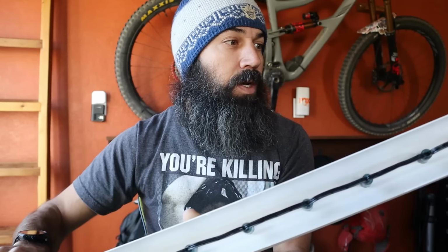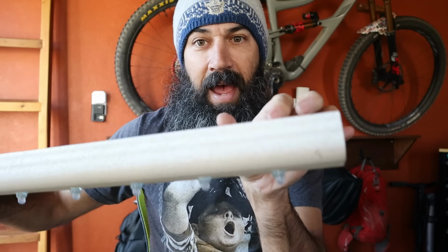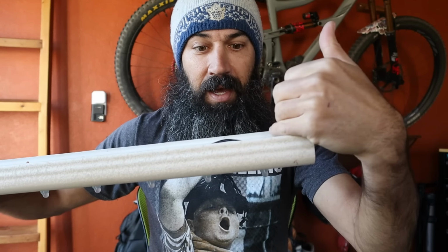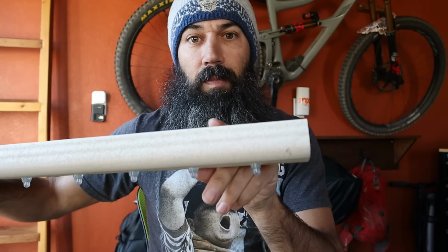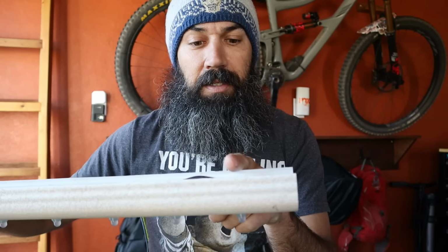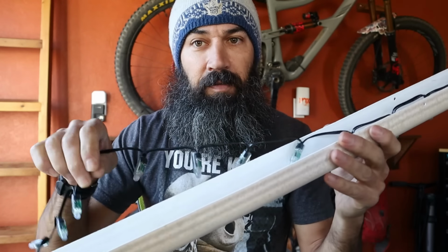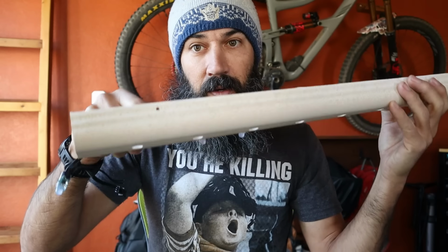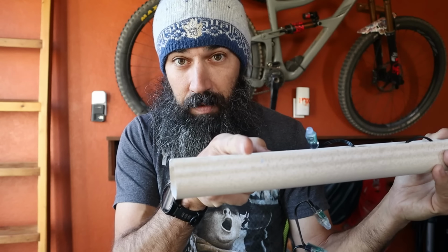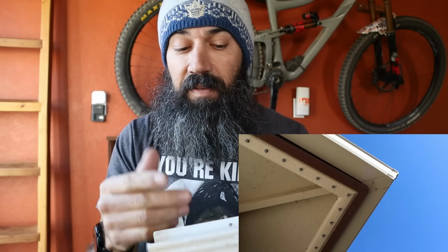So what I ended up doing was my starting hole, I always started at 1/2 of this distance. I did that so that when I put 2 pieces end to end together, it would end up at 2 3/4. So from the end to my first hole, I always did 1 3/8. So 1 3/8, start the first one, and then 2 3/4 all the way to the end. You'll fit 43 of these in one of these 10-foot lengths, and then at the end, I would measure 1 3/8 off of that one, and usually cut that at the end, unless I was doing corners where I would put 45s and stuff.